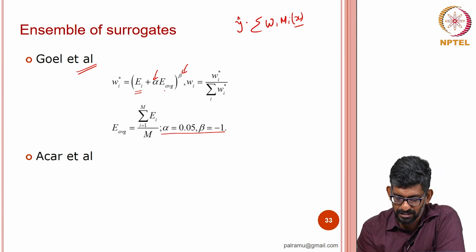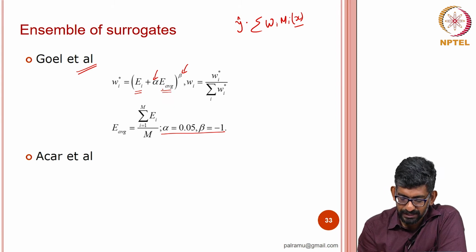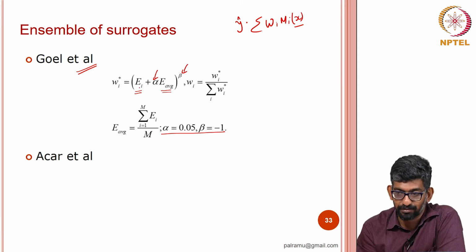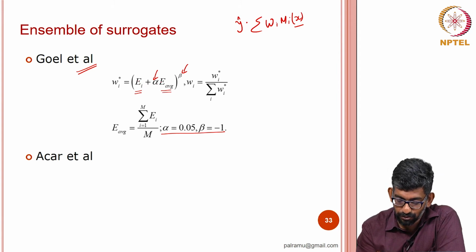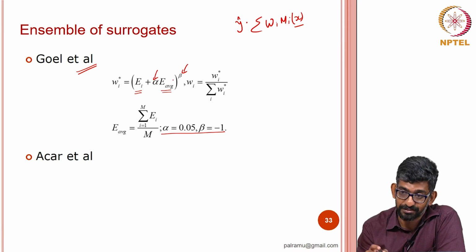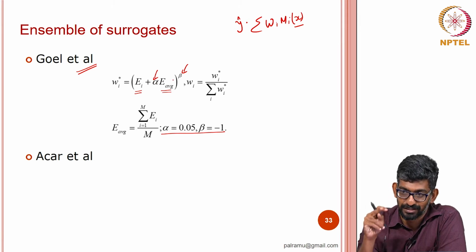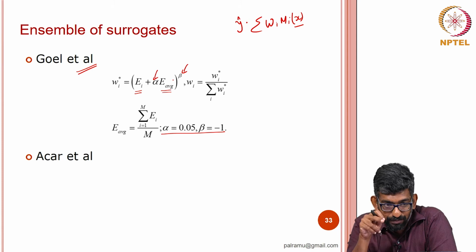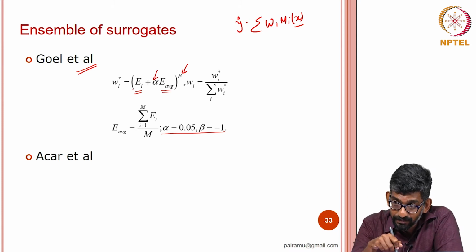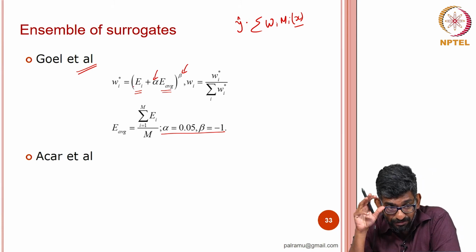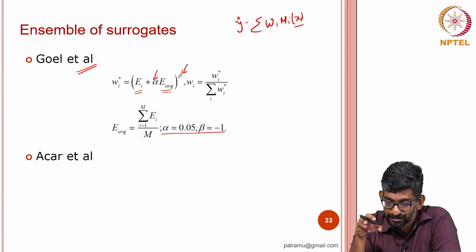What it gives here is an error for that particular metamodel, and here we are talking about the cross validation error, the PRESS RMS. It will also add some average from the other metamodels. There is an error per metamodel, which is your E_i, and there is an average error. If I have 5 metamodels, then I have 5 errors.